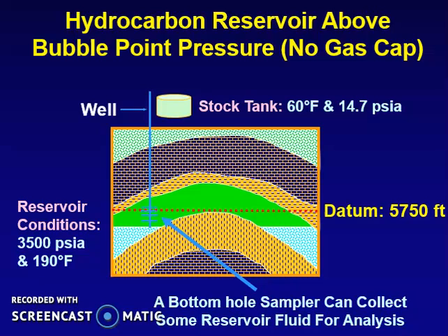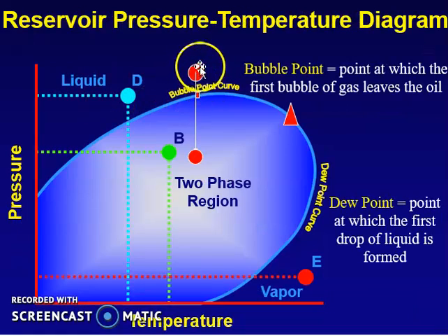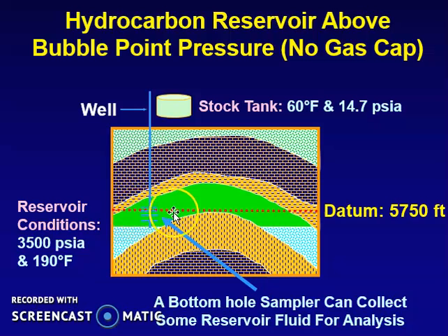Now, remember we talked again about the PT diagram. That's a very important diagram, and how the oil goes from 100% oil, if the pressure drops as you produce, the pressure of the reservoir drops and you go to the two-phase region. So what happens when oil travels from underground to the surface? You have a high pressure here, and as the oil comes to the production line inside the wellbore, its pressure drops.